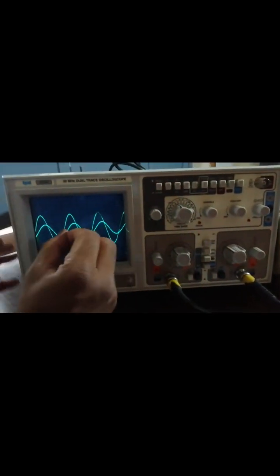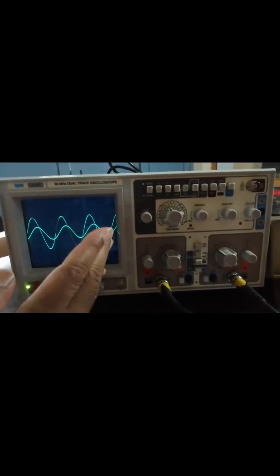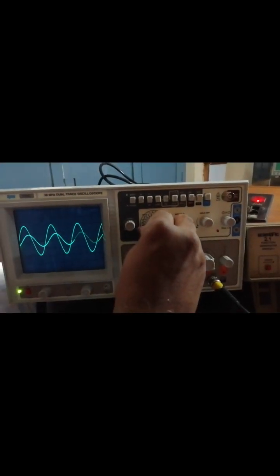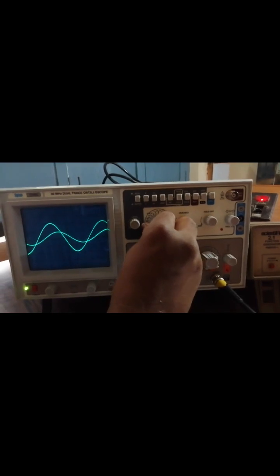So now let us see how to measure delta t. According to the design, you have designed your circuit in such a way that when the frequency is set to 300 hertz, the phase shift should be equal to 45 degrees. Let us see whether it is equal to 45 degrees or not. It is very small, so we need to measure it accurately. Let me move to the lower multiplication factor from 1 to 0.5, right?